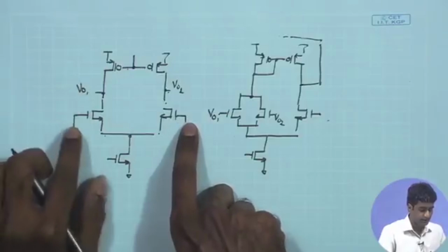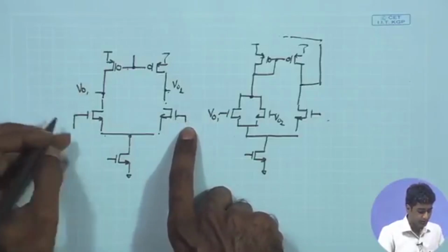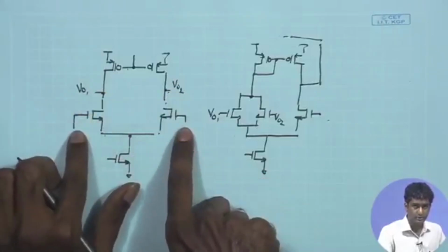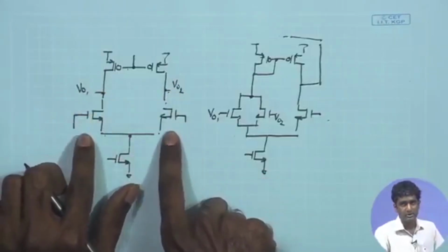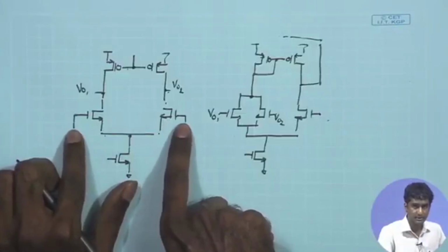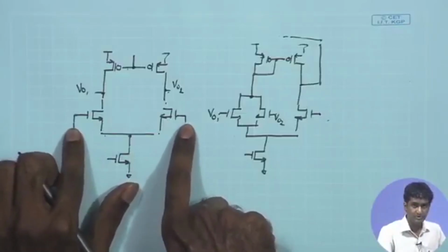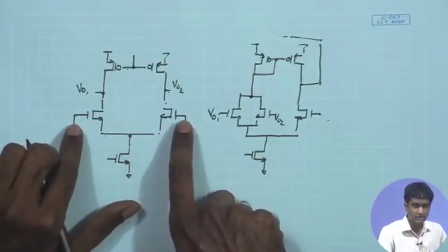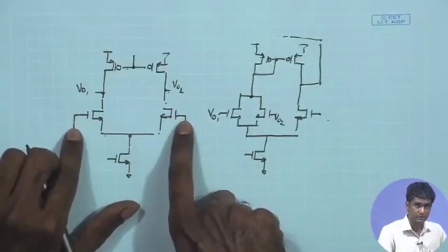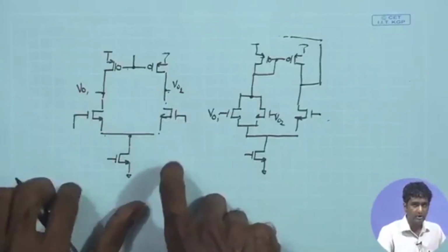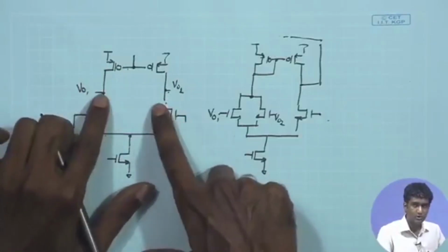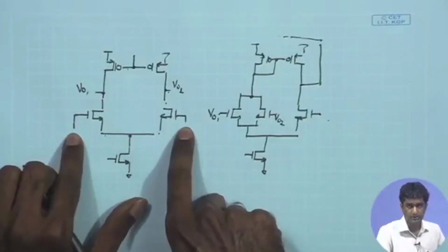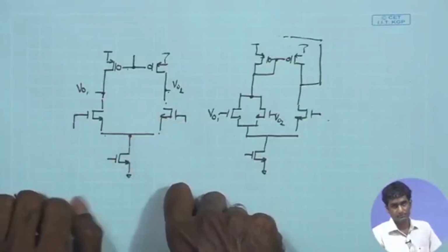However, if you look at the input signal over here, that if you are having an overall signal coming over here, it will induce some signal at this point also, unless you have some significant input capacitance placed over here for establishing an AC ground. Therefore, in order to ensure that this point is at AC ground, either we need to put a capacitor over here along with the RF, or the other option is that you remove the RF and then apply only ideal DC voltages over here with values equal to the closed loop condition.